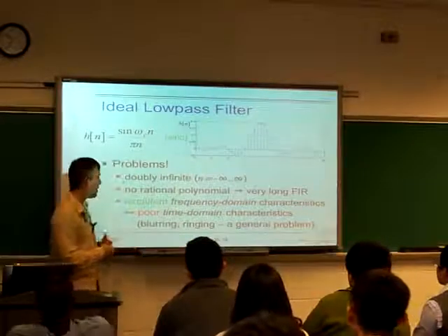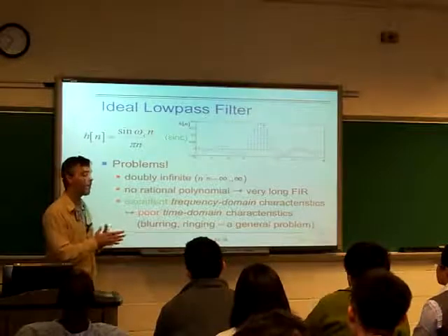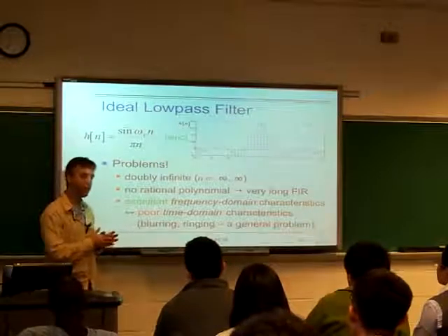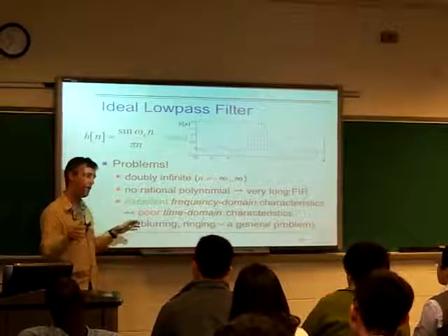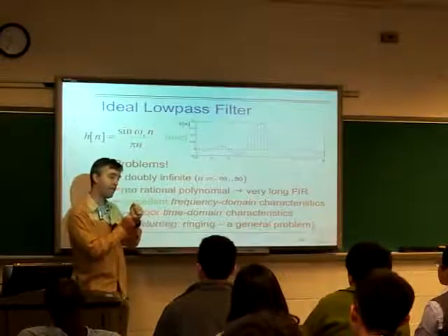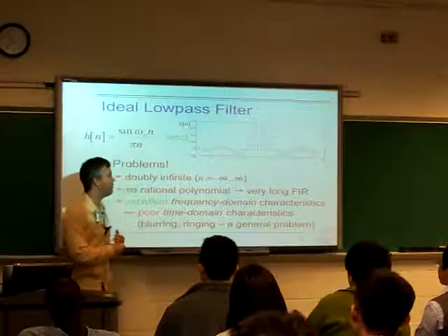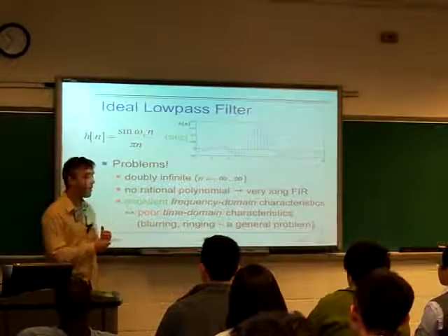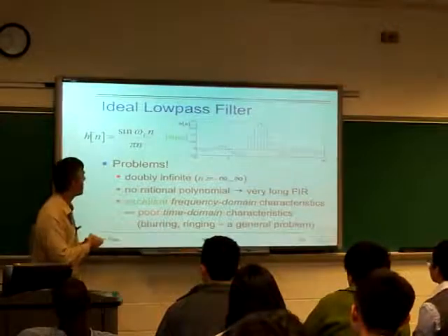And this is very typical, because of the complementary nature of the time domain and the frequency domain. If you try to limit in one, then you end up splurging out in the other, and vice versa. Here, we're trying to be very precise in frequency, and we end up blurring out in time. It works the other way around. If you try to make it very tight in time, then typically you end up with a very blurry frequency response.